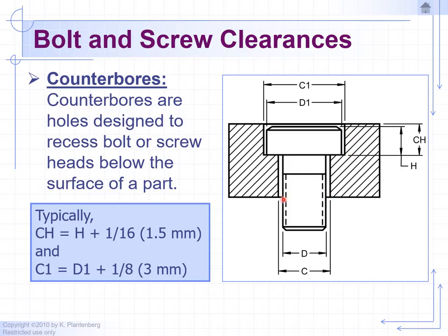That's where you drill a small diameter hole into a block, and then you come in and drill a larger diameter hole. That's referred to as a counterbore hole. And 99% of the time it's to accommodate a bolt and to hide the head of the bolt. So in some cases, like in the previous slide, if you don't want the head sticking out because maybe something may be on top, sliding back and forth, or you don't want it to get in the way of some other operation, then one thing you can do is hide the head of the bolt by drilling a counterbore hole.